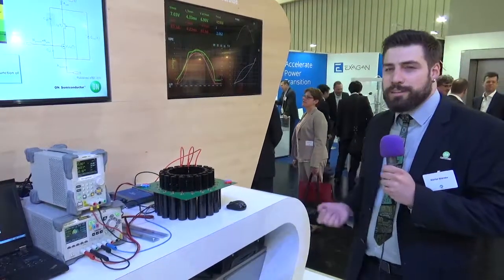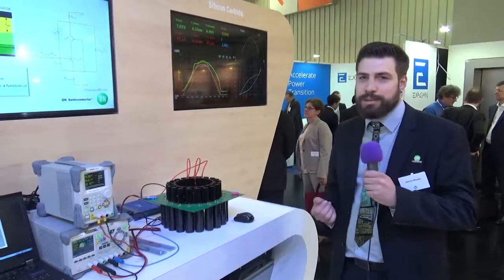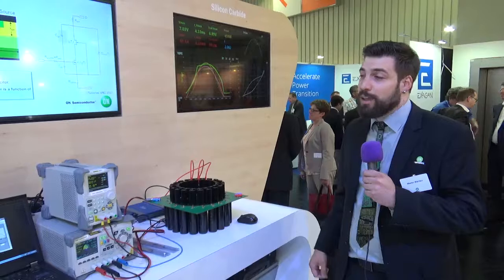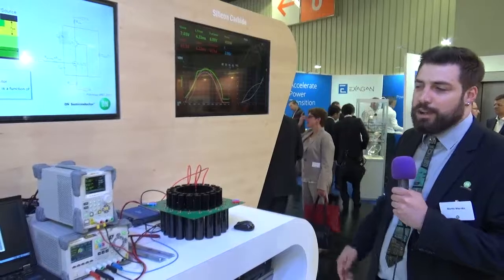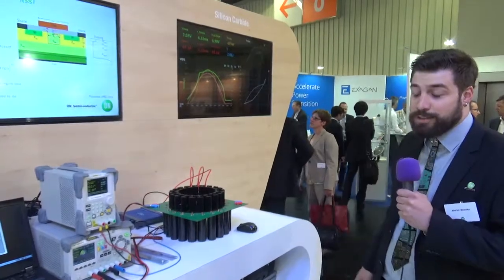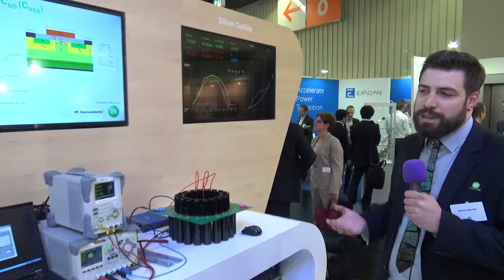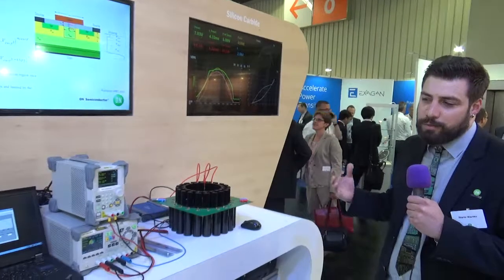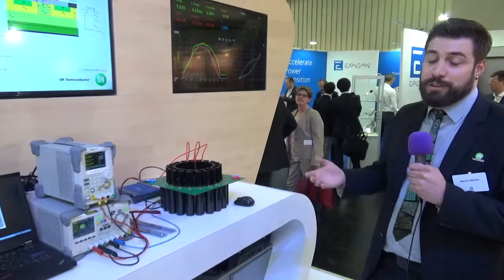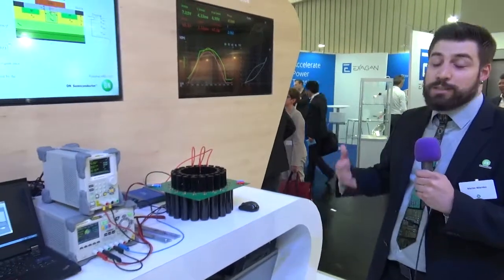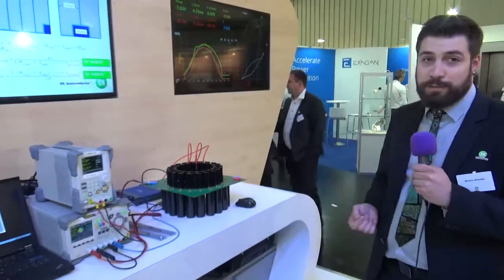That's why usually in the data sheets you will find half sine wave pulses, and you're giving a reliable data about the capabilities of covering a short current in these very high ranges of 8 times, 10 times of the rated current. So this is not the actual main focus for wide bandgap diodes anymore. It's not the bridge rectifier on the input of a power supply. It's more in switching power supplies where frequencies are much higher, where waveforms are completely different.